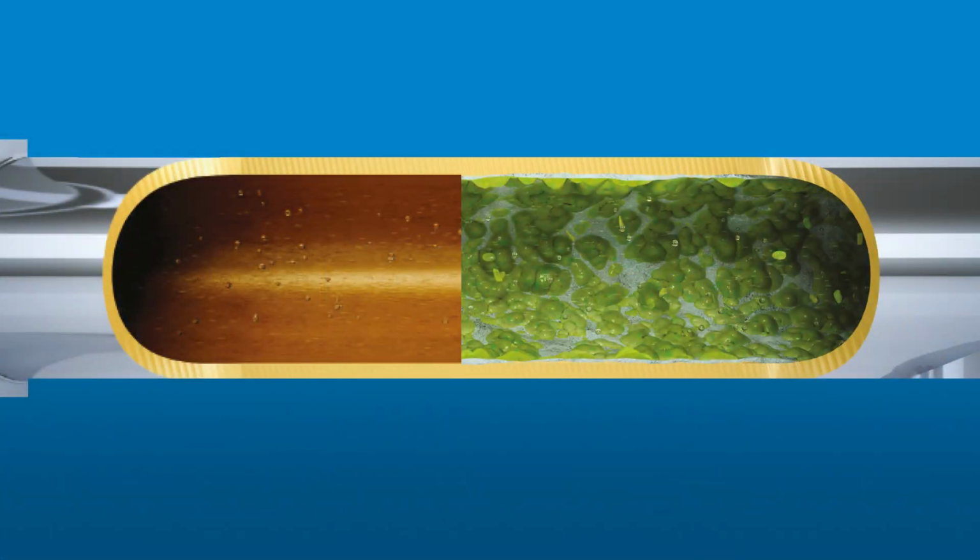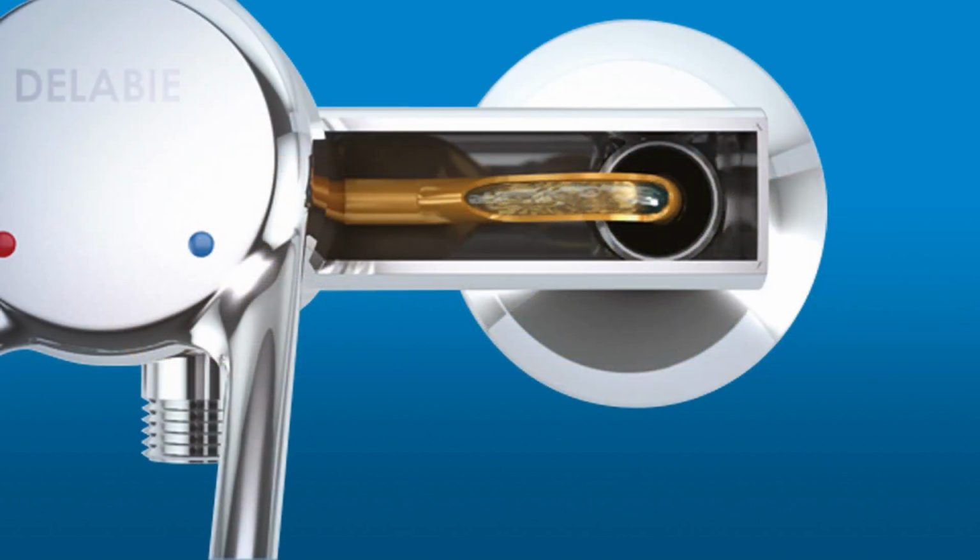Another example of an extremely effective solution is to limit the amount of water that circulates inside the mixer body. This is why Delabie prefers narrower water passages, which increases the speed of water in the mixer and reduces biofilm development. Also, there is less standing water once the mixer is turned off. So once again, bacterial development is limited. This is why some of our mixers are specifically designed with small tubes inside the body.